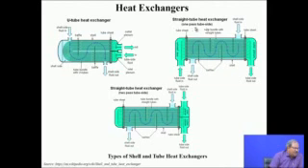One pass tube side means the liquid is going to pass through the shell and tube heat exchanger only once. So the liquid comes through the tubes, comes out on the other side, and so this is the tube side fluid in, it goes through the shell only once and is then collected at the exit.